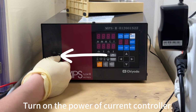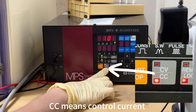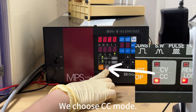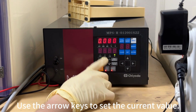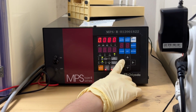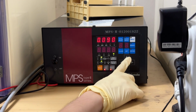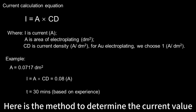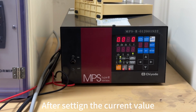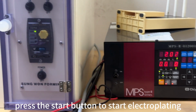Turn on the power of current controller. Here we can control the mode. CC means control current, CV means control voltage. We choose CC mode. Use the arrow keys to set the current value. Here is the method to determine the current value. After setting the current value, press the Start button to start electroplating.